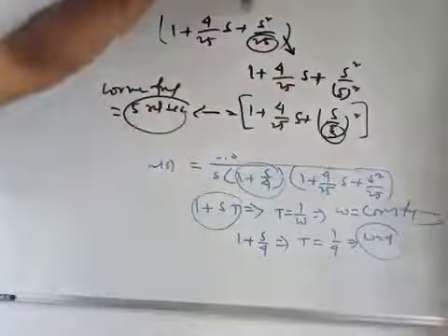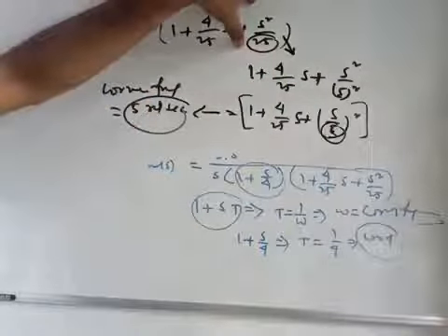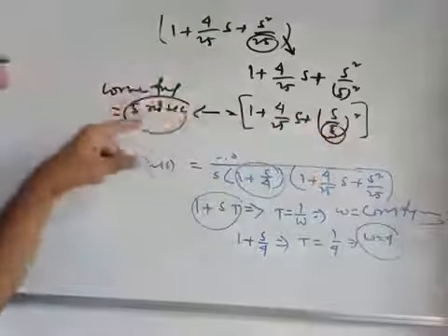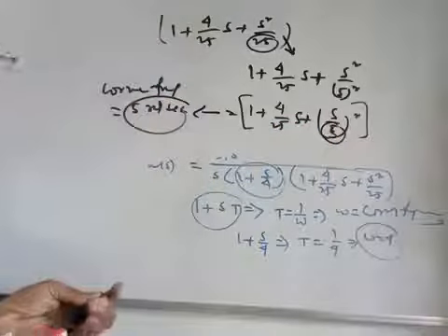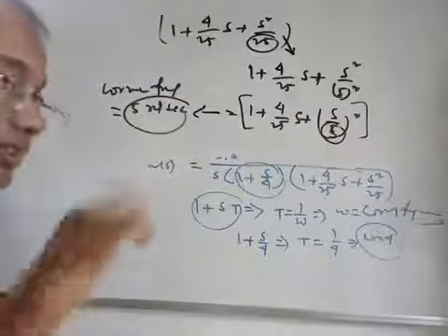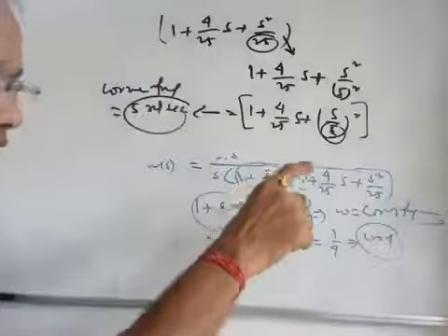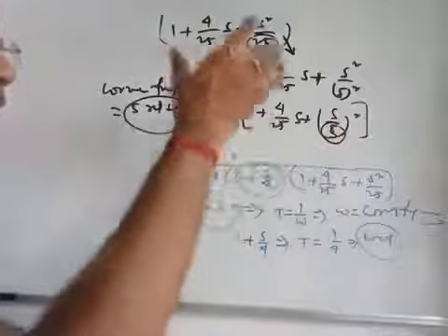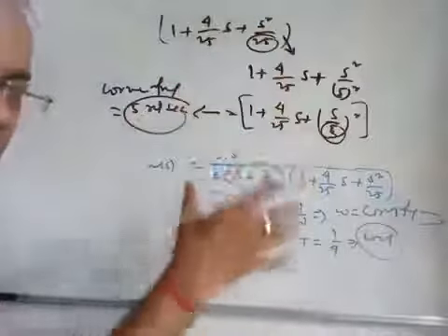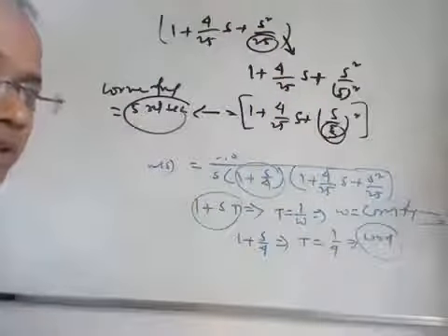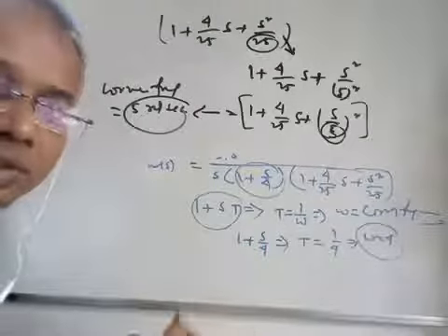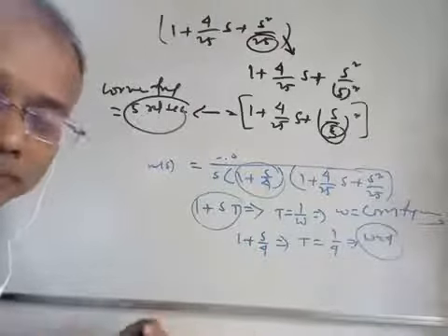If this is, say, s square by 24, that means root over of 24 squared. So omega will be root over 24 radian per second, right? So this is the procedure to get the corner frequency from the second order factor. Now we will have some expressions, that is calculations, to find out the initial magnitude. Then we will make the table according to our standard procedure to find out the Bode magnitude plot, right?